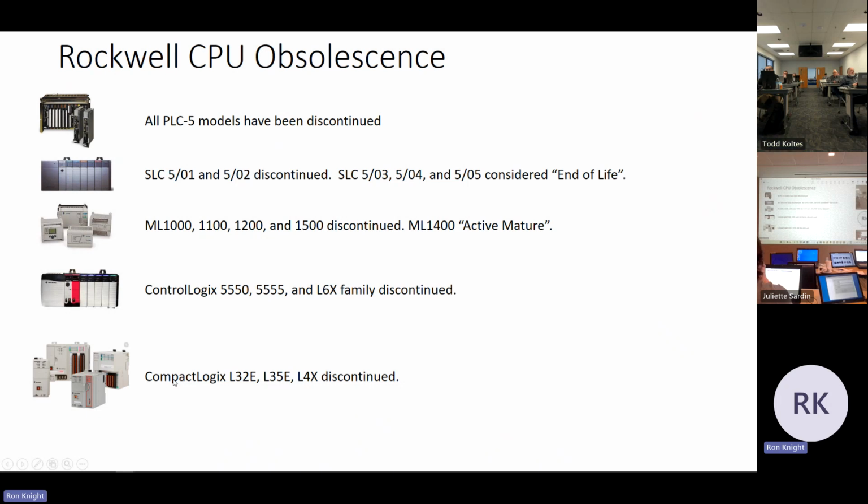The only difference though is the HMI. When you think about operating systems in computers and how quickly those change from year to year to keep up with cybersecurity and all that stuff, the HMIs are a little bit more highly affected than the PLCs. So I think that's why Siemens went with that whole new line of Unified Comfort Panels, to keep up with all those changes going on in the PC world. But the PLC world, we're a little bit more, I would say, slow to change.